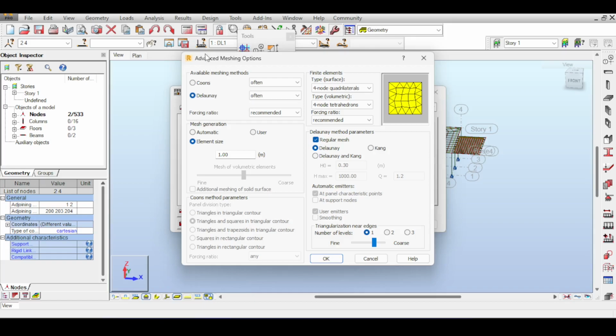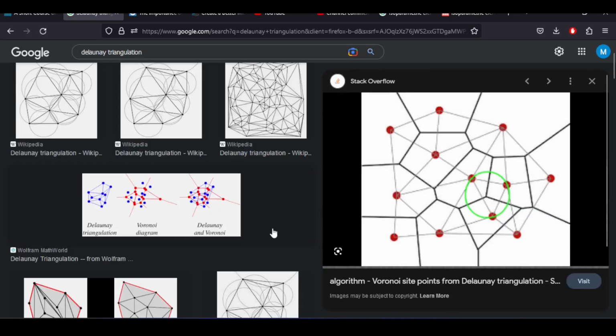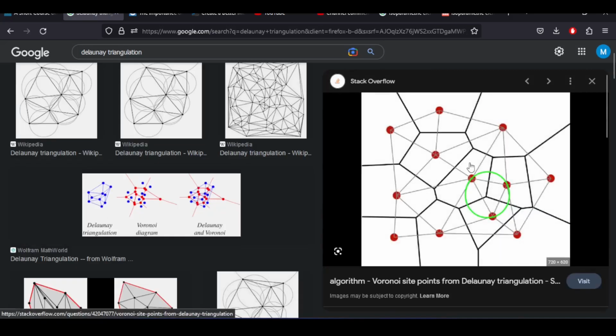This Delaunay triangulation is usually used in mesh generation, for example, in Autodesk Civil 3D, when you have ground data of a total station or level and you want to mesh to approximate and interpolate the intermediate values. It's kind of a cool concept where it basically tries to triangulate an element as well as possible, and actually is even used sometimes to create something called the Voronoi diagram.